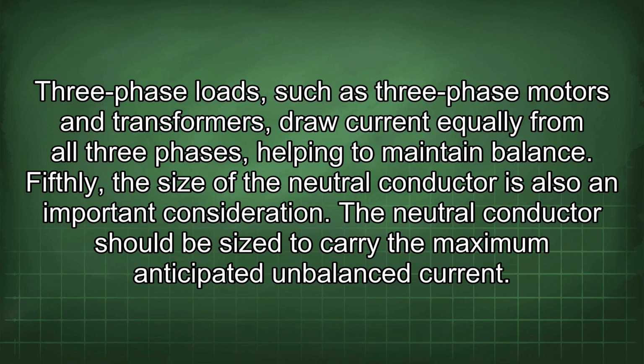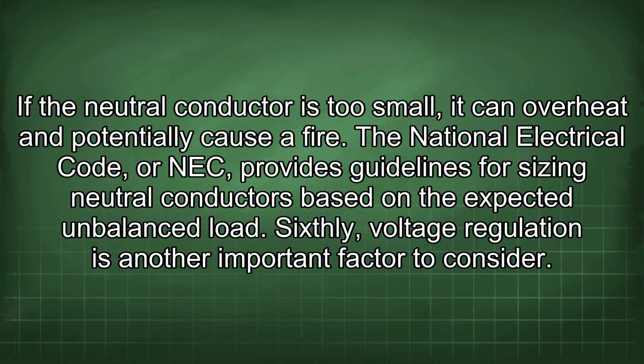Fifthly, the size of the neutral conductor is also an important consideration. The neutral conductor should be sized to carry the maximum anticipated unbalanced current. If the neutral conductor is too small, it can overheat and potentially cause a fire. The National Electrical Code, or NEC, provides guidelines for sizing neutral conductors based on the expected unbalanced load.